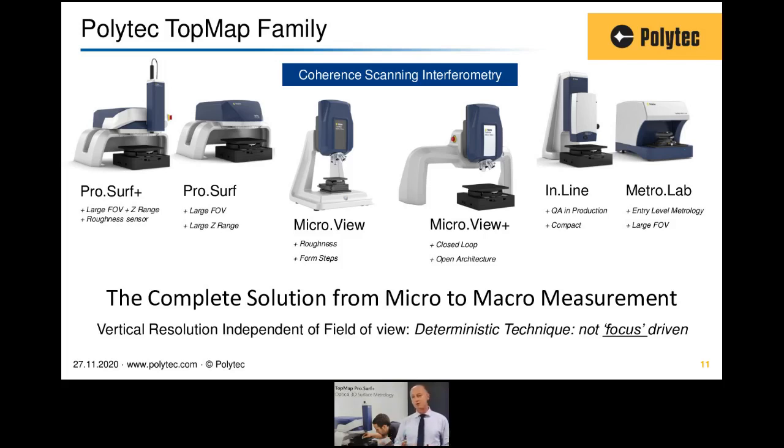But interestingly, for all our products, we have a Z resolution to the sub-nanometer or to the nanometer, irrespective of what technology we use, whether it's macro lens or micro lens. And this is due to how we signal process our data. All our data, we signal process using coherence scanning interferometry. So we refer to this technique as deterministic. It allows us to go beyond the diffraction barrier of light, and it gives us high Z resolution and high sensitivity to a surface.